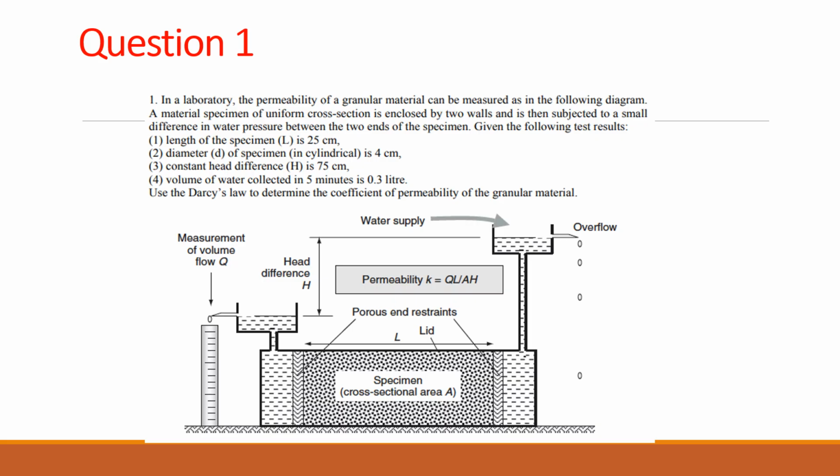So porosity is very important. So this experiment is for us to find the porosity of a material. So we put a porous material in this cylinder here, and we let the water flow. We create a pressure difference, so the water will flow from this side to the other side. By finding how fast this water is flowing, or finding the flow rate, we will be able to find the porosity. Am I right?